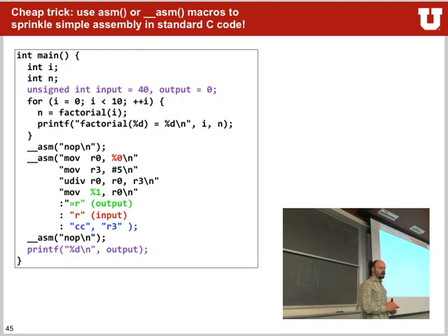And one last thing, if you really need to add assembly into your C code, there's a small little trick that you can use with the statement __asm that will execute assembly code. It's a little bit tricky on how the notation is, because imagine that the problem now is you have assembly code and C code. You have them to work together. So you somehow have to tell the assembler what your input is and what you get out from your assembly code. Because in assembly, you don't have variables, really. You have registers. But in C code, you have now variables. But you don't really know where all these variables are stored at which point in time.